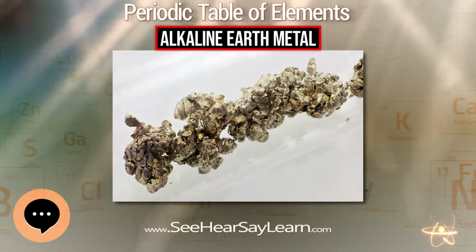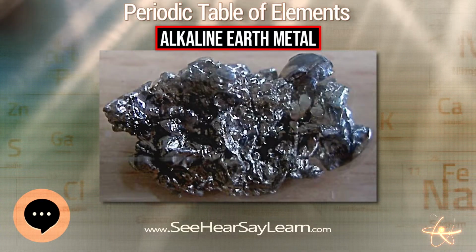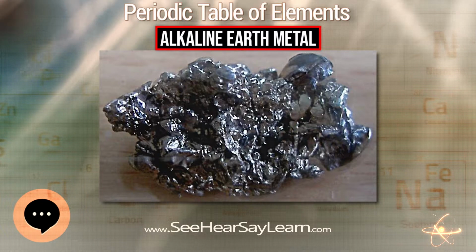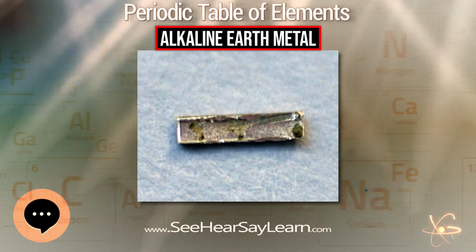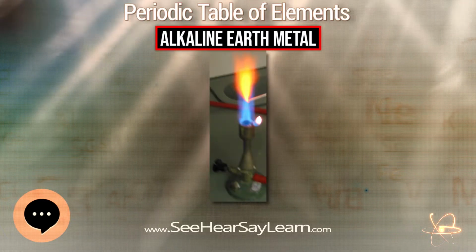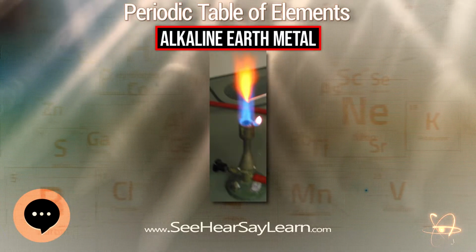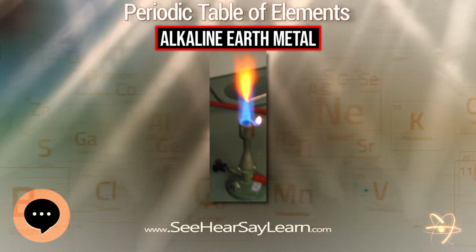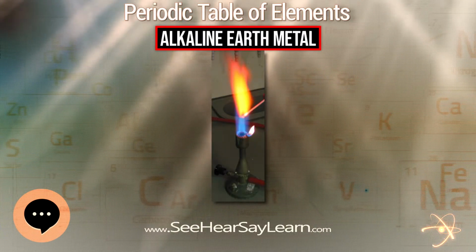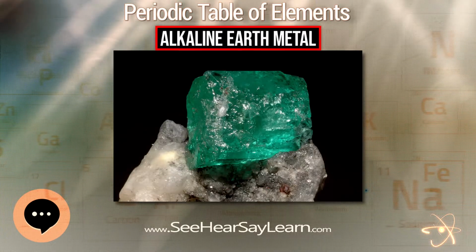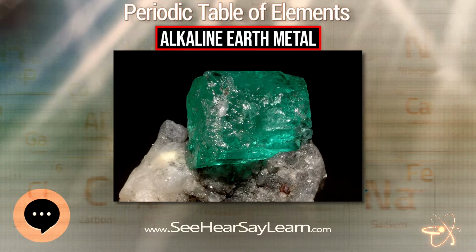Most beryllium is extracted from beryllium hydroxide. One production method is sintering, done by mixing beryl, sodium fluorosilicate, and soda at high temperatures to form sodium fluoroberyllate, aluminium oxide, and silicon dioxide. A solution of sodium fluoroberyllate and sodium hydroxide in water is then used to form beryllium hydroxide by precipitation.